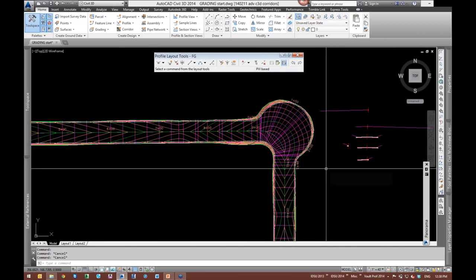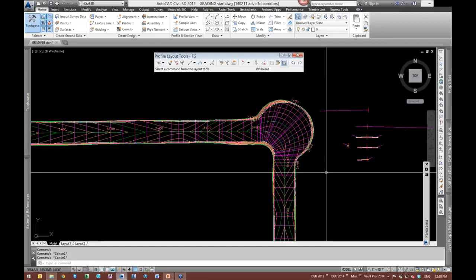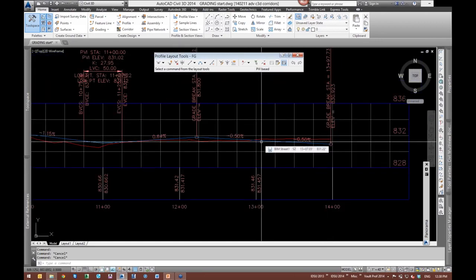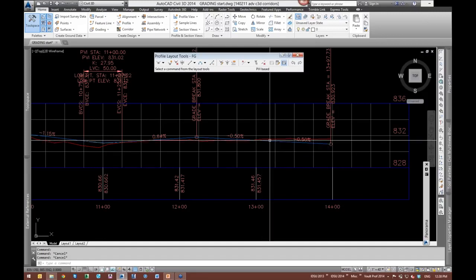So this is the idea with auxiliary corridors. The idea is that you build a drainage surface and create surface profiles from it. And if possible, you build that auxiliary corridor right on top of the main baselines, your full actual corridor. That's what makes it really dynamic. Because when I make that profile change, that affects not only auxiliary corridors, but also full corridor.